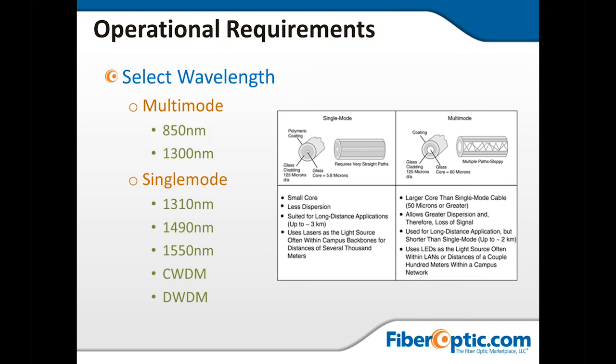The single mode is going to give you much less dispersion. We used to say there's no limits, but realistically now we're looking at CD, chromatic dispersion, and polarization mode dispersion, giving us some limits, but usually you'll see some kind of hub site about every 100 kilometers with no degradation to the system at all.